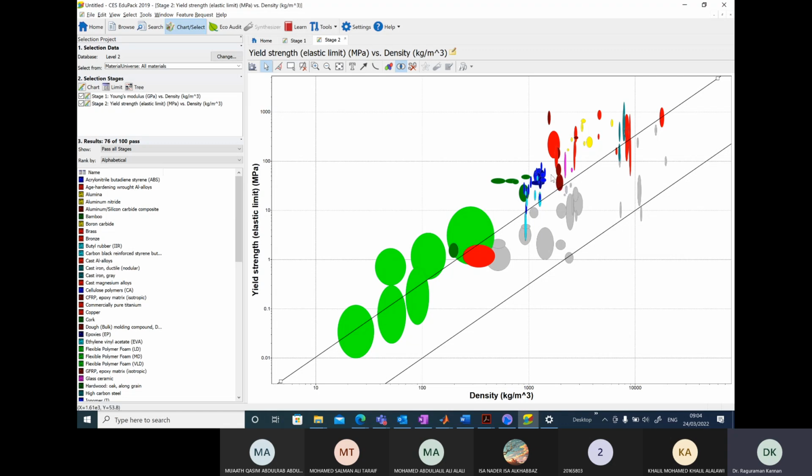the line. So of course there should be a minimum value of the strength. The strength of steel is usually in terms of megapascals, and the strength is also provided in megapascal here. Again, this is on a logarithmic scale. Remember, this is 0.1 megapascal, 1, 10. And if you actually think about it, the steel material has around 200 megapascal. So maybe this is the point here. So we can have a limit of the strength as 100 megapascal.